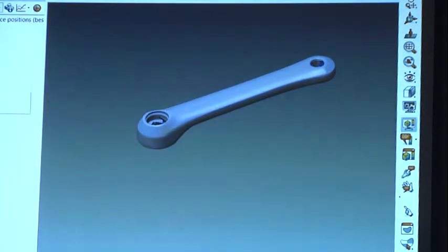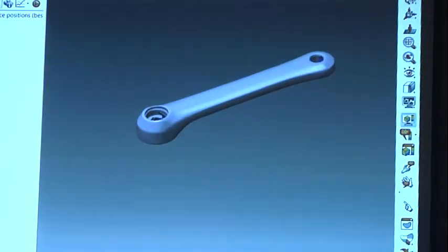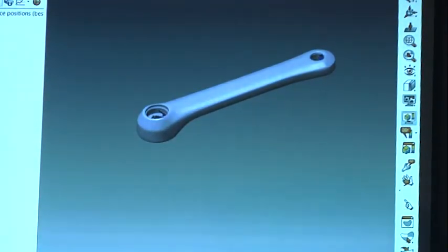And from this point, it's exactly as if you would have scanned it with a single device position or single setup. You can import your CAD, complete your inspection workflow. Now, to go one step further, I told you we keep these objects here in order to be able to update this. And that's the case. And we keep all the links like that in order to be able to use multiple pieces workflow with this inspection workflow, where we have 2 setups, we need to realign them. So I have a full inspection workflow here.